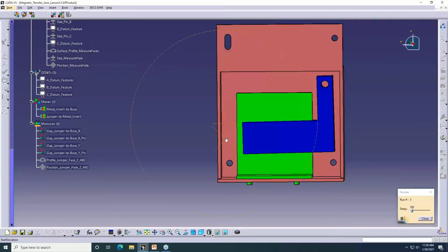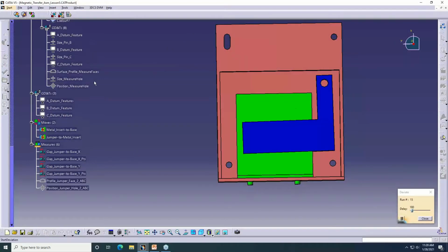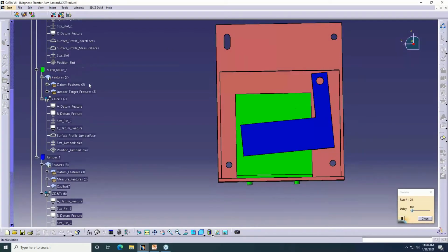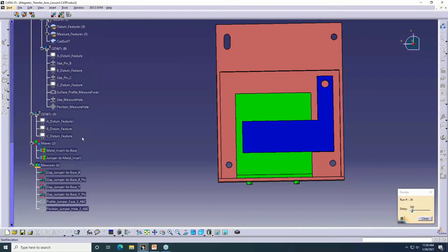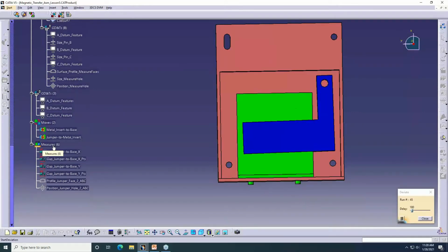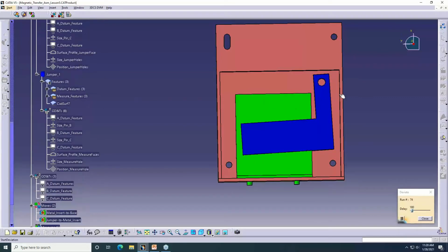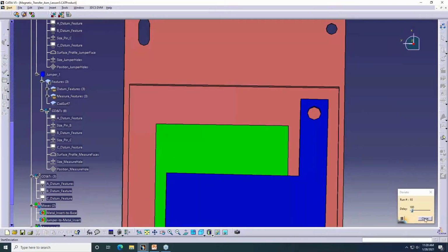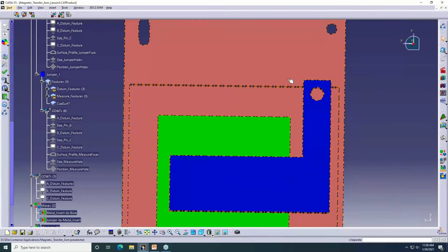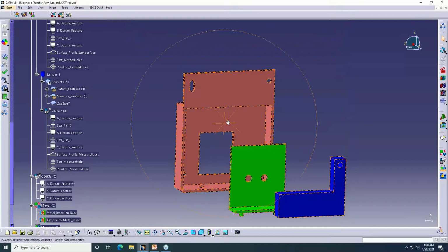This is taking a look at all of that GD&T we have applied in our model, and I will cover a little bit of GD&T addition. We're going to be creating a new measure after we take a look at results, just to see how simple it is to add a new measure in here. I will cover a little bit about that, but for right now, we're just taking a look at what is actually applied so far. And again, we're looking at this gap up here so we can see how that's changing right now. I'm going to go ahead and nominal build my model again.